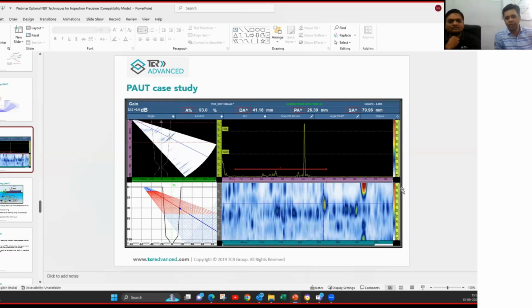Weld joints are butt weld joints. Those joints, like insulation support ring to shell joints, are never inspected, right? So those are all covered under one roof and one single test in acoustic emission testing. That is the first advantage, whether it is a tank inspection or any pressure vessel equipment.